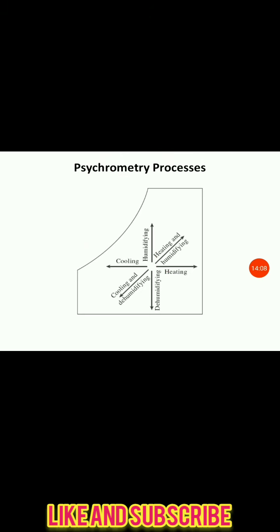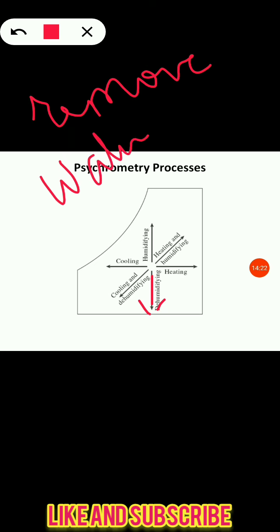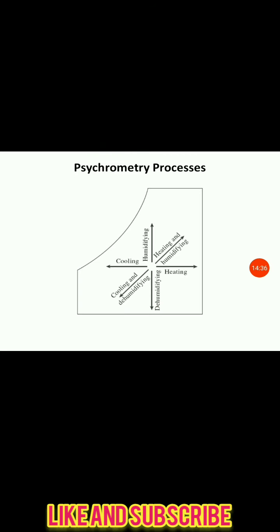Then next is the psychrometric process, the dehumidification. In the dehumidification process, basically we need to remove the water vapors from the moist air. In order to remove the water vapor from the moist air, we can use an absorbent or adsorbent, so that water vapors can be absorbed, or rather we can cool the surrounding air below its dew point temperature.